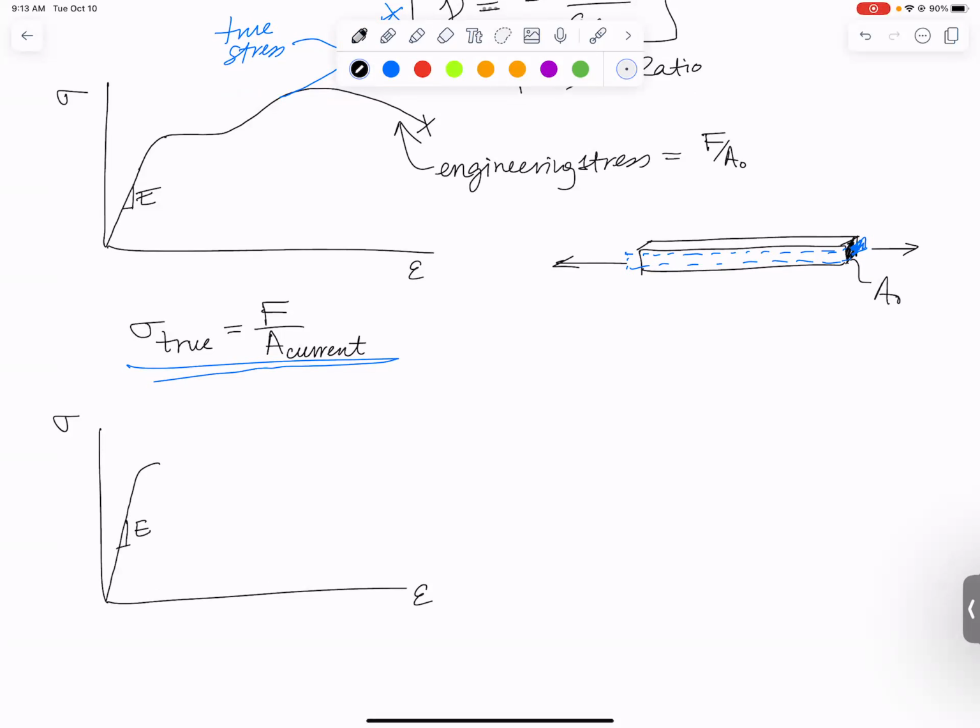that we're going to define the yield stress by coming over here a very small strain. Specifically, we're coming over here 0.002, which is also 0.2%. And we're going to draw a parallel line, and wherever it intersects the stress strain curve, that is what we're going to define as our yield stress. And in this class, we will never go past the yield stress because we are assuming that all strains are small, all deformations are in the linear elastic range. This 0.2% means we're not technically completely perfectly linear, but with experimental error, we're pretty linear.